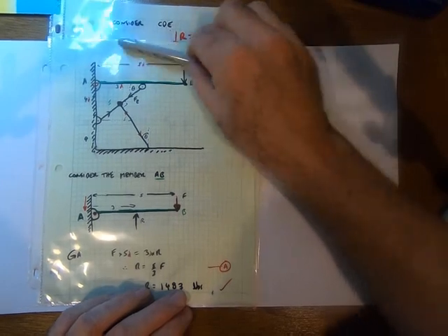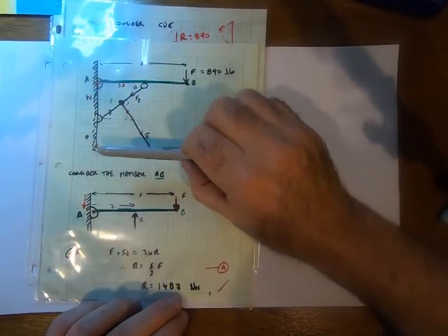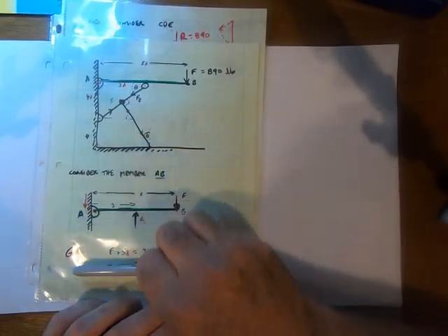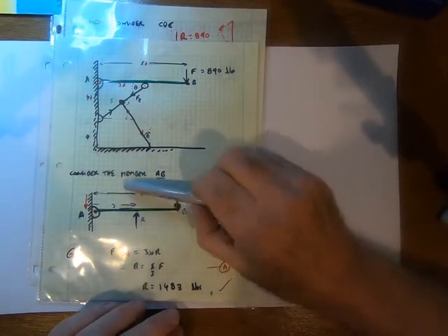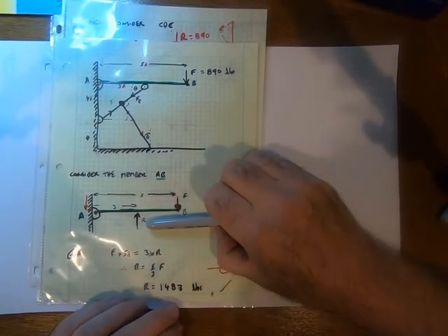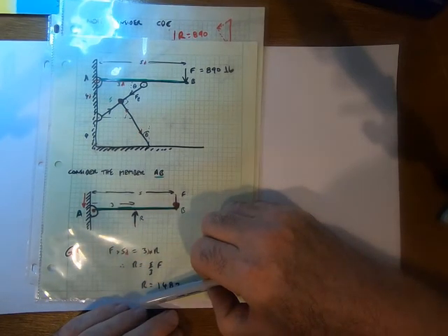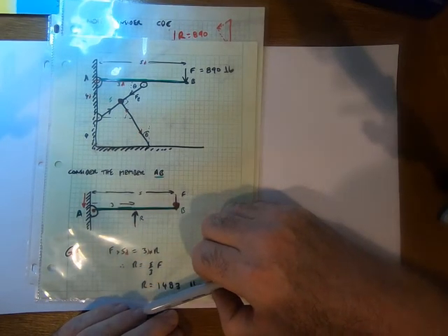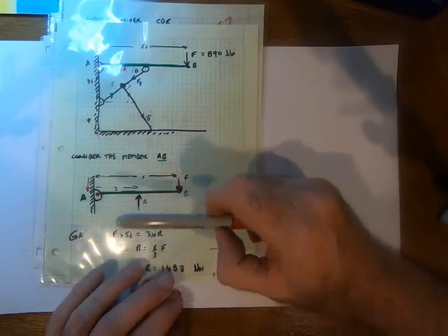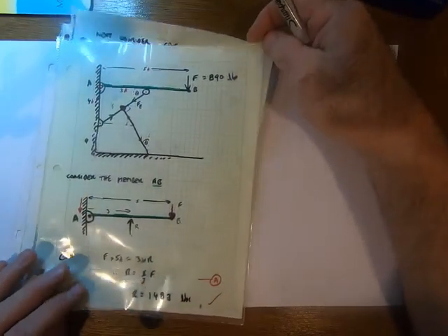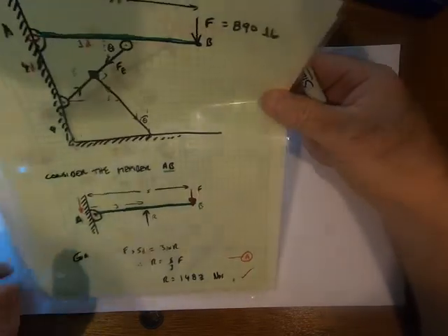Draw the sketch for informational purposes, and then for the analysis, break it down into the free bodies and look at the forces on the body on its own, and then solve and work your way through. Try and keep it all algebraic as long as you can, so that you can later come back and optimize it. Okay, so that's it for today, for the little statics review.